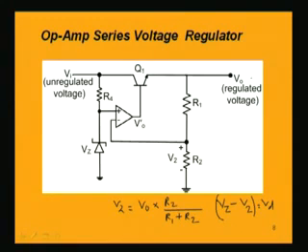So in this circuit, which is using an op-amp as a comparator, we have seen that the change in the output voltage is balanced again by bringing it back to the earlier value, and that can also be verified for a decrement of the output voltage.